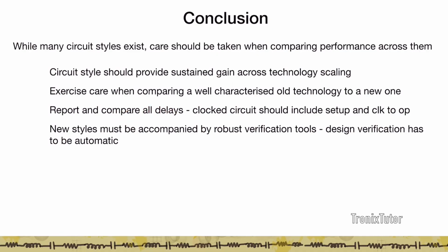You should report and compare all delays and ensure that you have captured all the delays in all the critical paths. And do not forget clocked delays, especially if you're using clocked and domino circuits. And the last part is, when you think about a new style, it's important that you think about verification, because today almost all of verification is automated. And so you need to figure out an easy and automated way to verify your design in case you're using a technology that is not static CMOS.